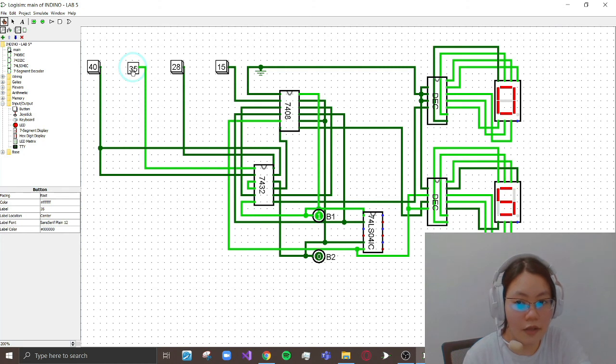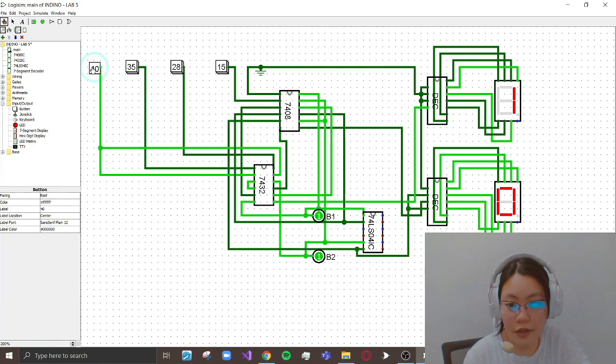And our 7-segment display shows 5, which is the absolute value of 30 minus 35. And lastly, we have the switch 40. In our encoder, we have 1, 1. And for our 7-segment display, we have 10 because 30 minus 40 is negative 10. So the absolute value of that is just positive 10.